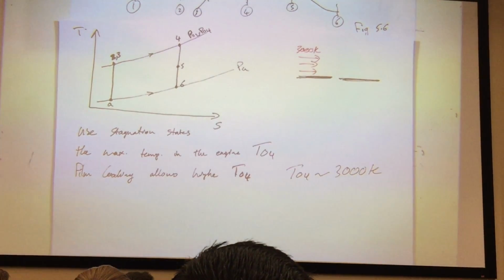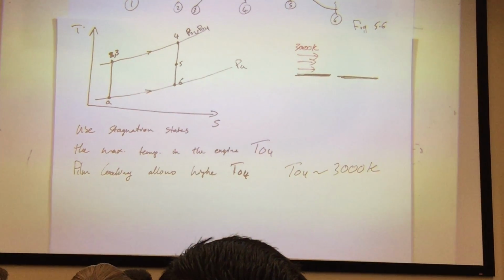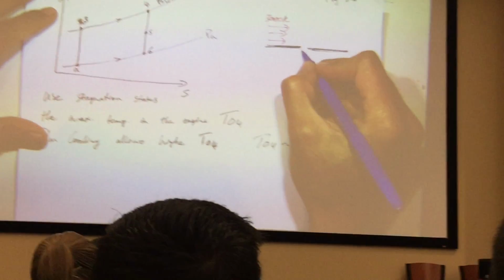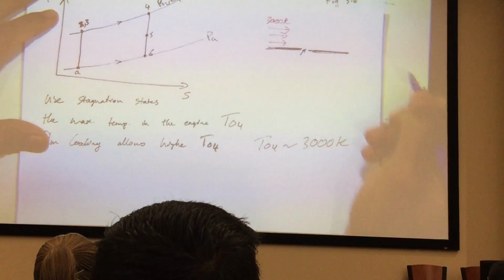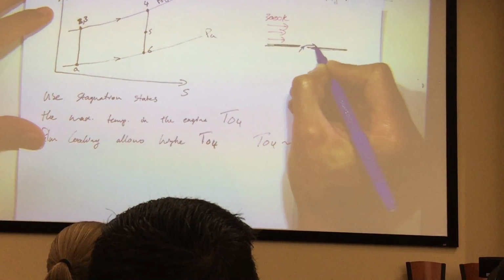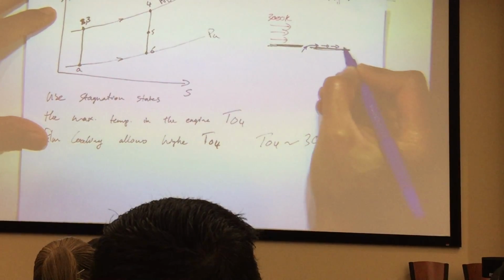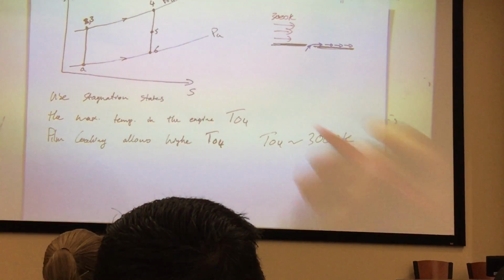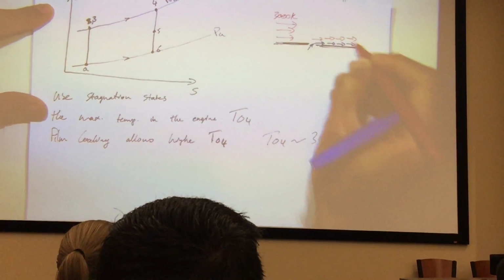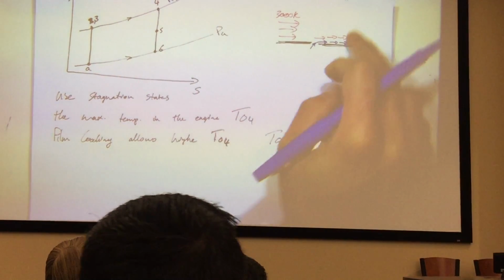So how do I keep it cooled down? I use almost rounded jets, an array of multiple jets that I issue right there. And these are low momentum jets that follow the flow path and keep closer to the surface relative to the hot core right here, and they end up shielding my wall from the hot gas.